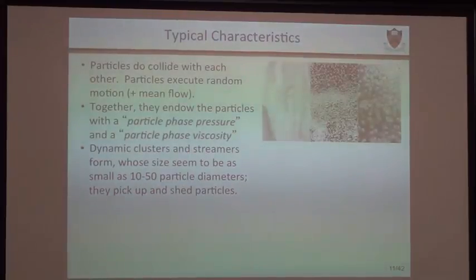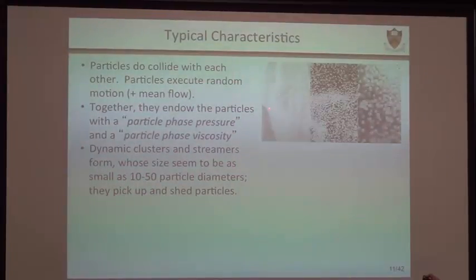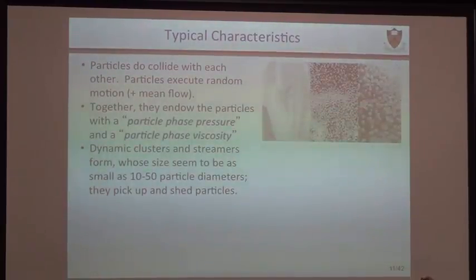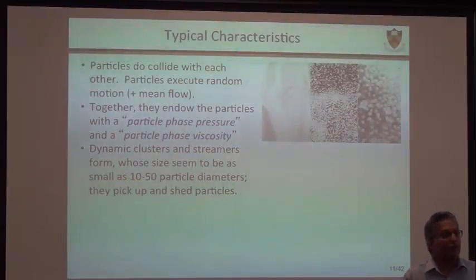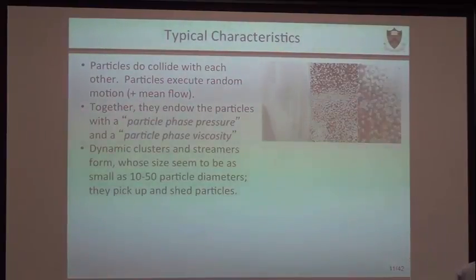And from a chemical reaction point of view, if you form a cluster, and all the gaseous reactants are outside, the particles in the cluster may not see a reaction. And therefore, the effective utilization of the particles is going to be a lot smaller in that case. So you can expect that your transfer rate, your utilization of the catalyst, and your reactor performance are very affected.